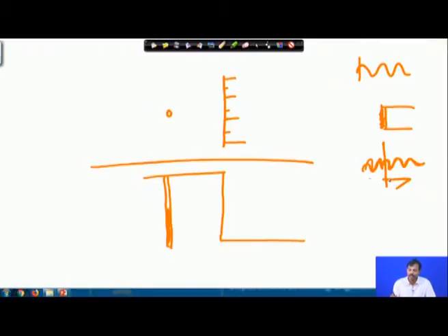Initially from the explosive entering into the rock, the compressive pressure given by the wave is very high. So, the compression is very high and the rock compressive strength is less than that compression pressure, and that is why the rock fails under compression at that side.